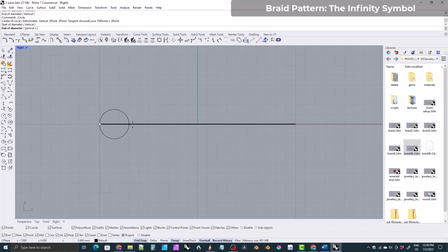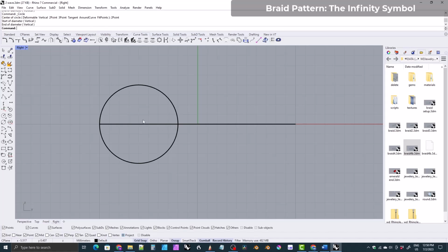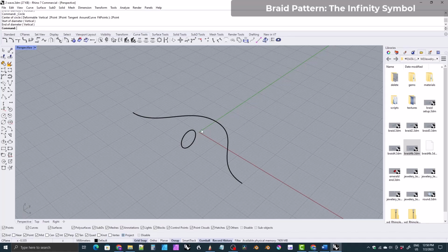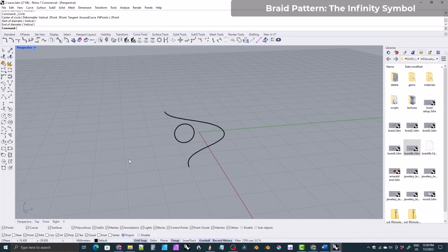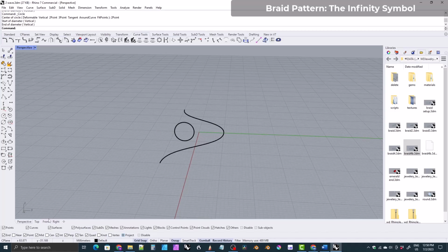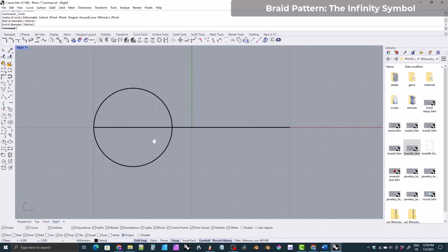Okay, so we're just going to snap and snap to the grid until we are 2 units away from the origin. So right there. And that will be 8 units over. So 1, 2, 3, 4, 5, 6, 7, 8. All right, because we had project turned on, it has placed it here along the y-axis. Okay, if we had not had project turned on, it probably would have snapped it from here over to here, and it would have been very strange looking. But let's go back to the right viewport.